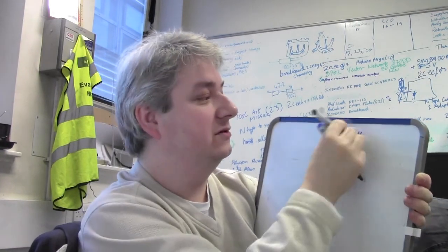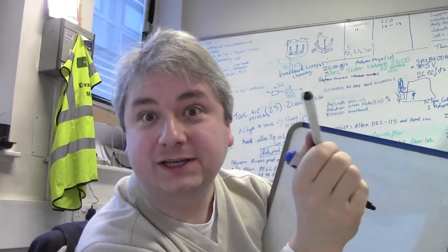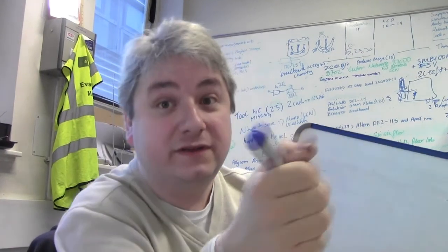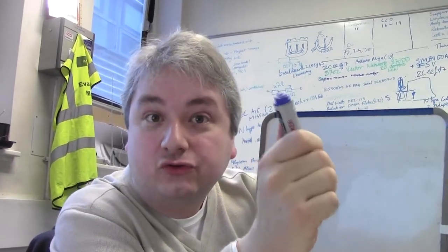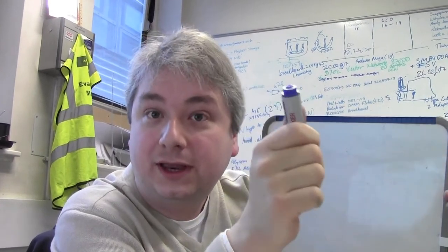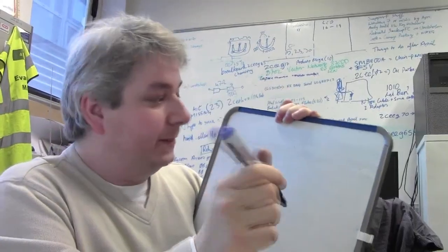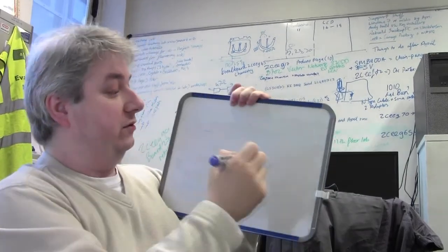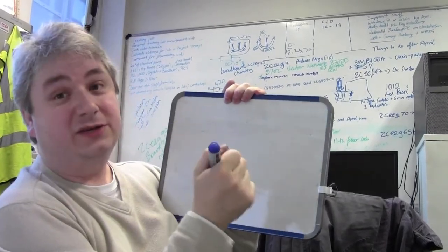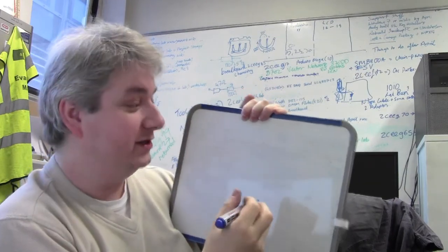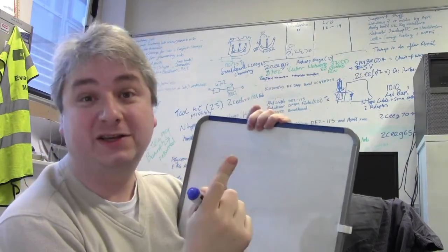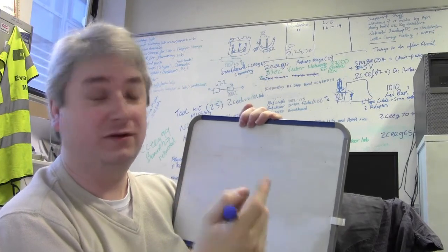The only difference is we use a transistor. You can use a FET if you want. I'm going to do this example with a little BJT to control the LED. How to use a transistor? Well, we're going to use it as a switch, basically. We're going to saturate the transistor, have it turned on maximum, so we get maximum current flowing through our transistor.